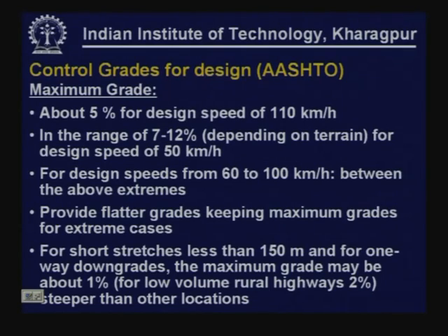We should try to provide flatter grades as far as possible. The maximum allowable grade should not be used all the time for design. We should try to provide flatter grades, keeping the maximum grades for extreme situations where terrain conditions are difficult or site-specific problems are there. So, we should keep the extreme values for those cases.